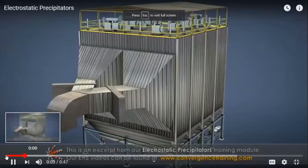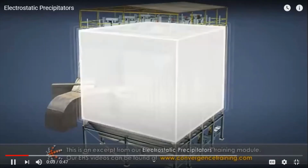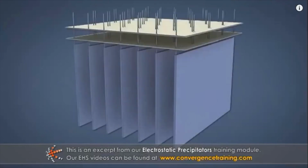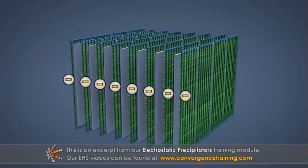A precipitator operates in an enclosed chamber. Inside the chamber are collection plates that are connected to the grounded outer frame. Positioned around the collection plates are discharge electrodes. The electrodes are negatively charged with high voltages and are insulated from ground.